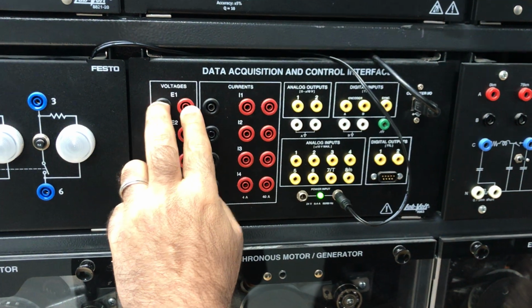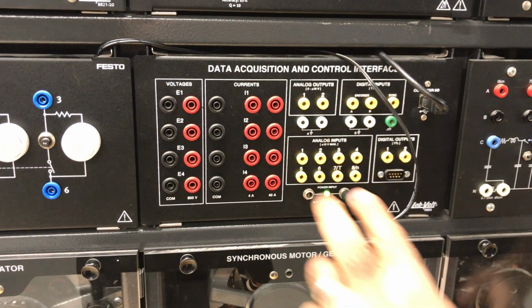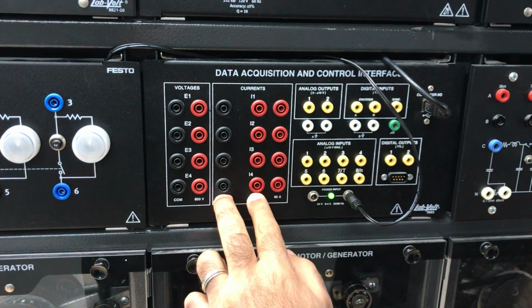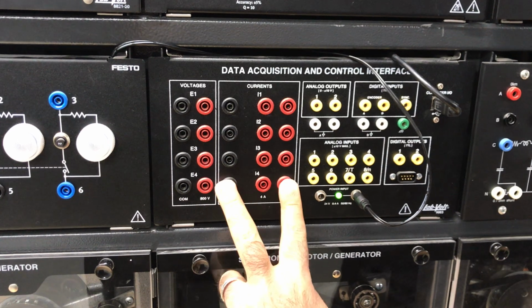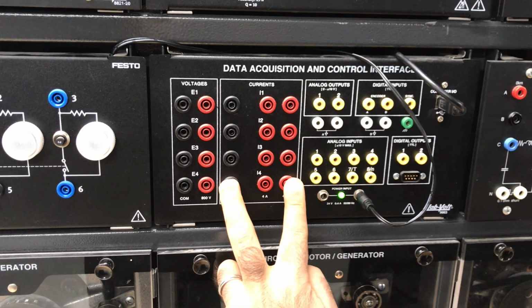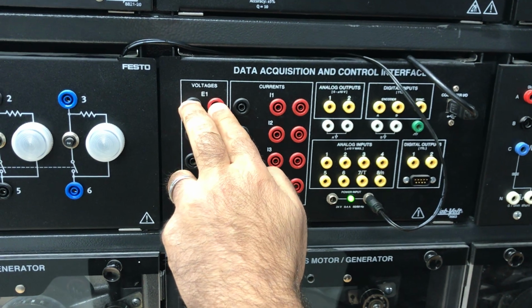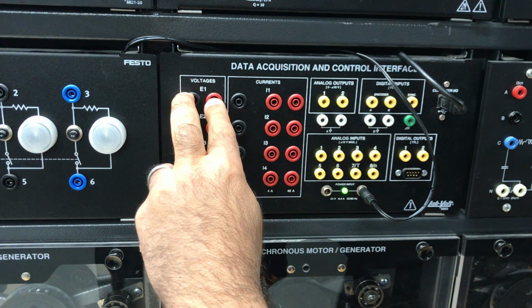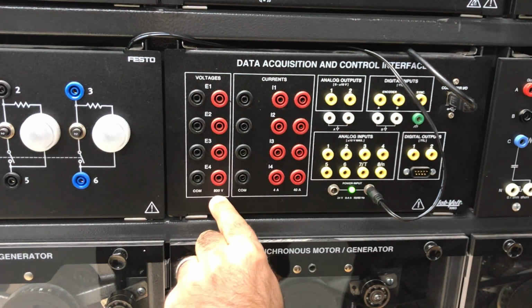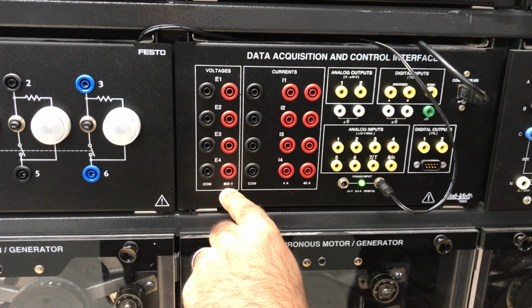So any two of those are used as voltmeters. Any two of those are used as an ammeter for a maximum of 4 ampere, or a maximum of 40 if I'm using those. So I can use this as a voltmeter and I can use this as an ammeter. This is connected in series and this is connected in parallel. Pay attention, the maximum voltage that this one is measuring is 800.